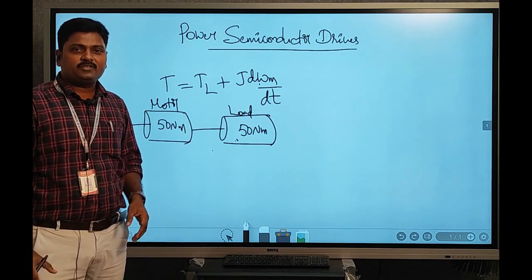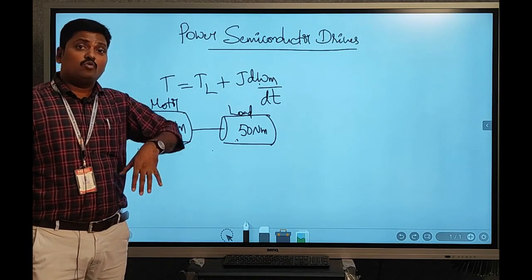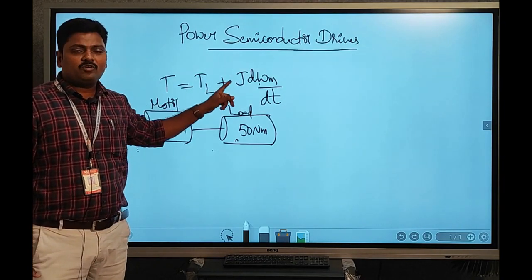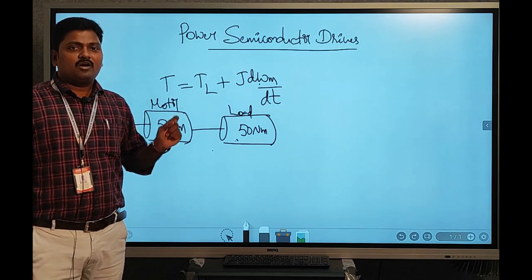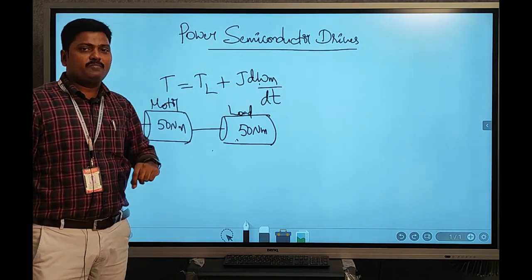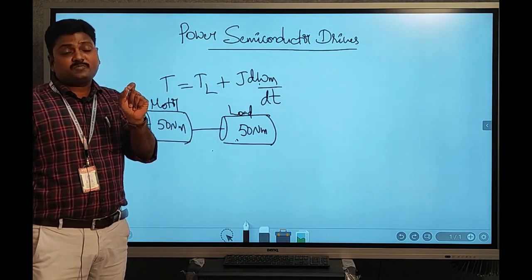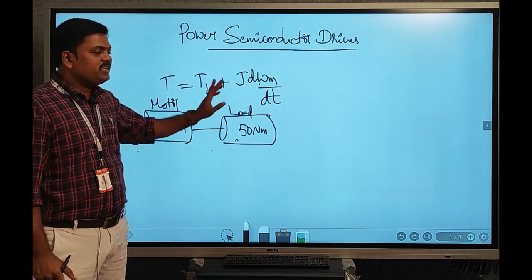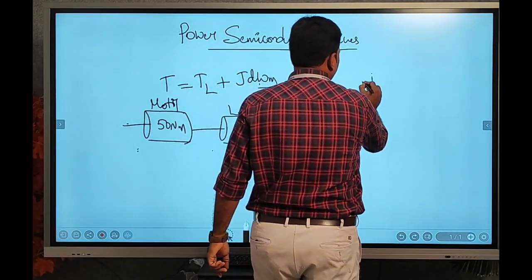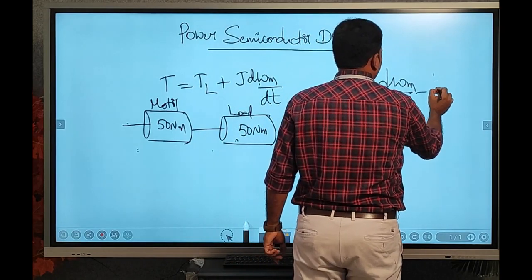in a particular direction. So it depends upon the weight of the motor and the weight of the load; each offers a different moment of inertia, and will have a different amount of dynamic torque. So dynamic torque not only depends on the change in speed with respect to time, it also depends on the moment of inertia, or the inertia it offers with respect to its own weight. That is why J is also added. So J d omega by dt is nothing but the dynamic torque.